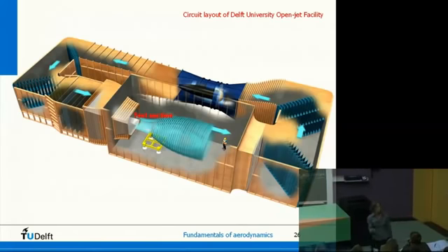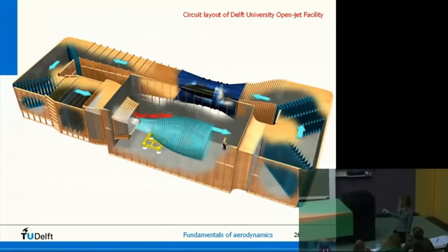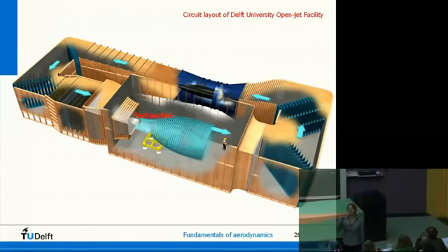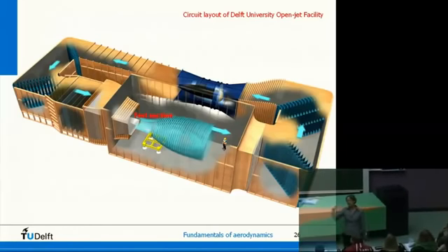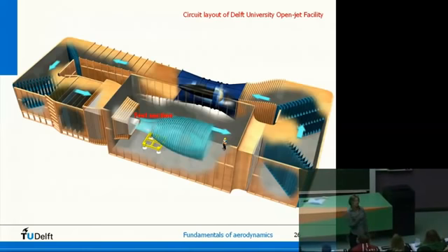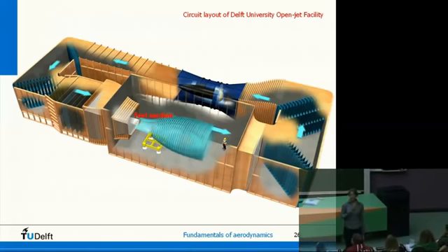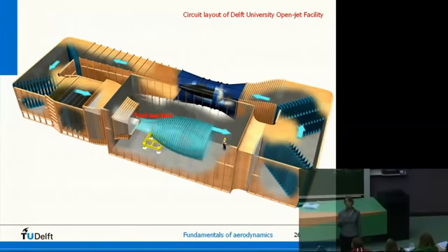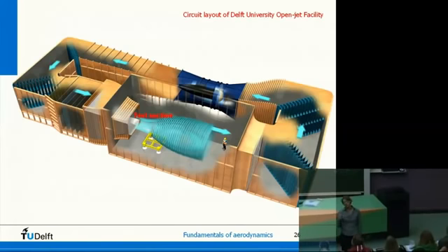Then the flow is blown over the object here, and we measure pressures, for example, forces, but we can also do particle image velocimetry, have smoke here or particles, and using laser light, illuminate it, take pictures, and then the whole story for my colleagues starts because you have pictures with particles at certain time instances, and you have to then correlate them, and that's quite a mathematical exercise. Like I'm solving the equations for flow directly on my computer. He's solving these relations for the particles.